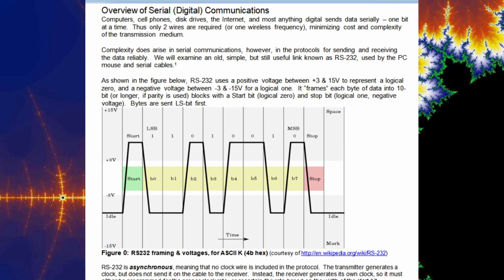It's a little bit different than the PowerPoint slide that talked about data framing, because that only looked at things in terms of ones and zeros. If you were to look at this same example, you would have to flip it top for bottom, end for end, to get what it would look like in that other chart. So this is very specifically an RS-232 transmission. You can see here the positive voltage and the negative voltage. We sit at the negative voltage at rest, and so it's what we call idle. It's waiting for the transmission to happen.